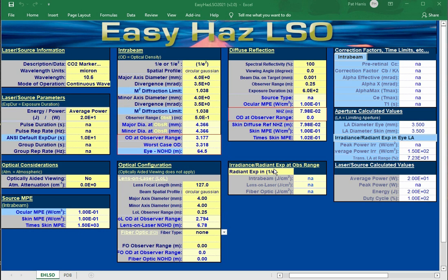Okay, so where the Q-switched YAG and Q-switched fiber lasers are really better equipped for doing marking on metals because of the high peak power pulses, CO2s are really excellent for marking non-metals particularly. So let's get started talking about this.